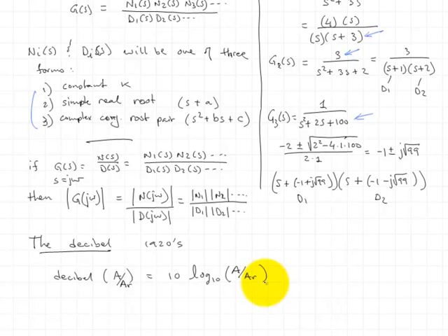is the reference level. Okay, and if these were quantities of power, which they would be, say we had 1 milliwatt as our reference level, then if we were trying to represent 1 watt in decibels, we would take the ratio between 1 watt and a milliwatt, that would be 1,000.